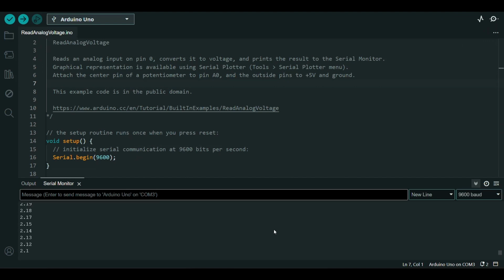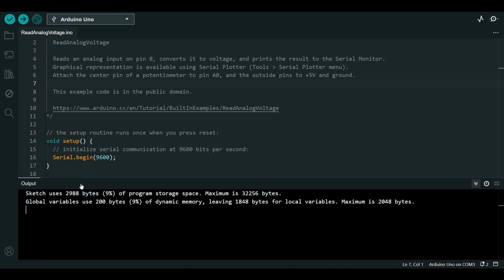The microcontroller of the board has a circuit inside called an analog-to-digital converter, or ADC, that reads this changing voltage and converts it to a number between 0 and 1023. When the shaft is turned all the way in one direction, there are 0 volts going to the pin, and the input value is 0.